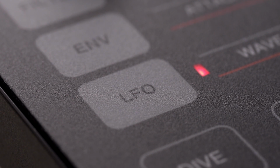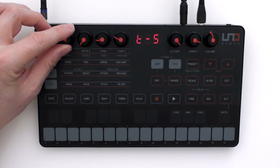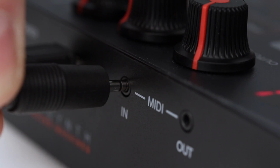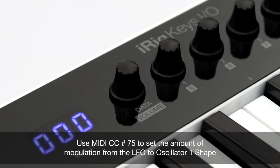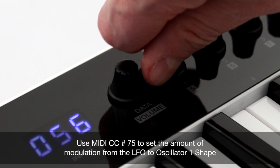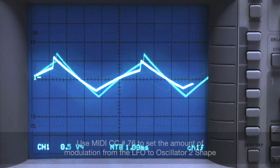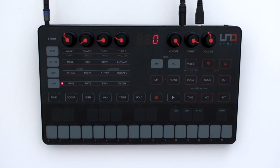We can use the LFO or the filter envelope to modulate the shape of the oscillator wave over time. Set the oscillator wave shape to the sawtooth setting, which is between the triangle and the square. This will allow the LFO to modulate the full shape between triangle and square at its maximum modulation value, crossing through the sawtooth shape along the way. Then to get the LFO to modulate the shape of oscillator 1, you must send a MIDI continuous controller number 75 message from your computer, mobile device, or external MIDI controller, such as a controller keyboard. Use MIDI CC76 to modulate the wave shape of oscillator 2.